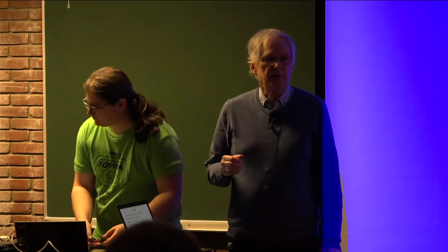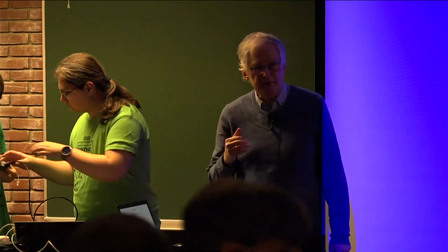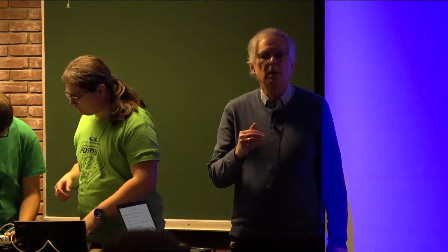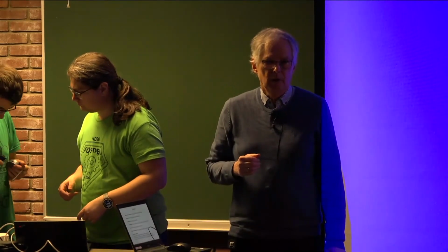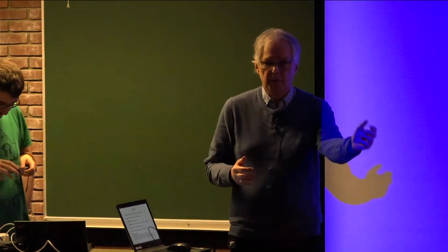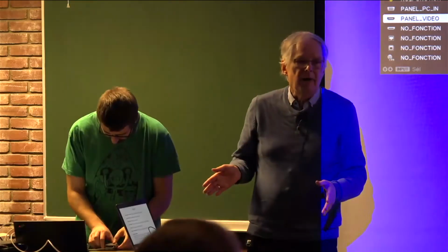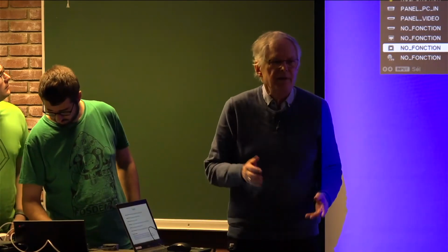This text file is loaded. You put into your Spice netlist a single line with a specific model, and this model loads the state machine. That's it for these simple things. For the complex ones, you could, of course, write state machines in C code if you want to. Then you have to do this translation.